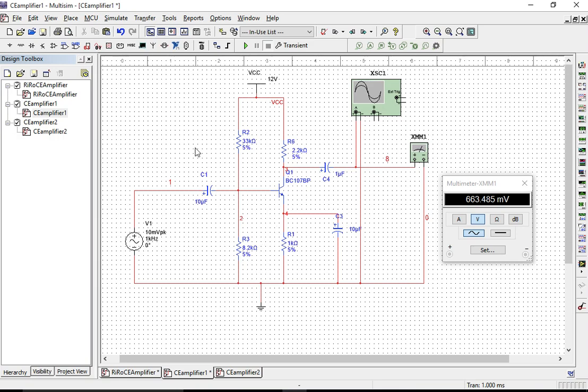For the same circuit, we are going to now calculate the input resistance. For that process, what we have to do is add some input resistance, which is variable, that is a pot. So same circuit I have modified and created here like this with some pot value. If I press capital A or small a in the keyboard, its value will increase or reduce, or I can use this slider also here.